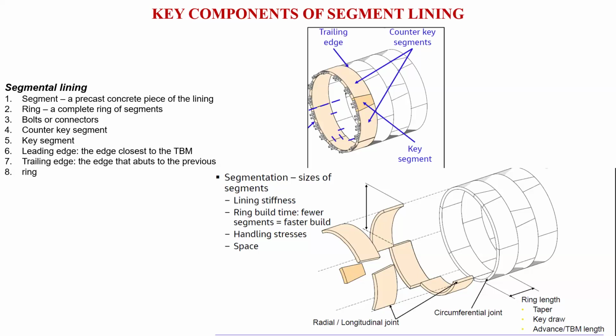Also, it depends on the groundwater you have and what the groundwater pressure is. If the groundwater pressure is very high, how many bar of pressure is it applying on the TBM face? That is also very important. Hyperbaric intervention is a very controlled intervention. It has to be done very precisely. If you work in Lucknow, we never did hyperbaric intervention, because the groundwater table is 25-30 meters below the ground. It's very self-supporting ground, with very high cohesion and very high shear strength properties. So even the ground itself is stable.